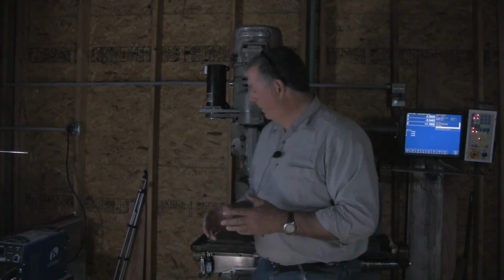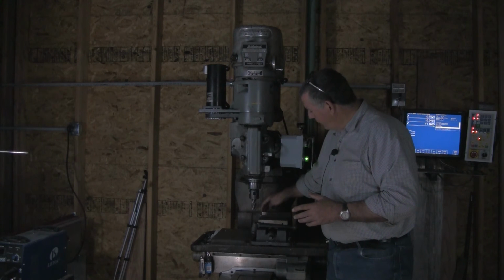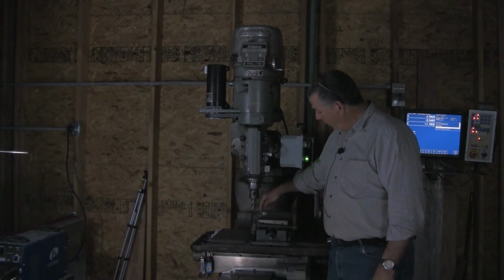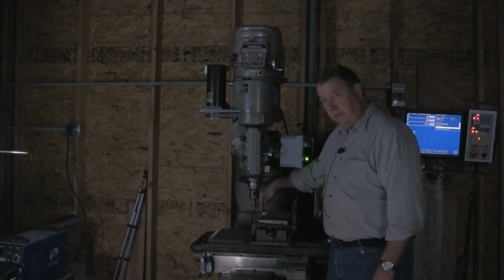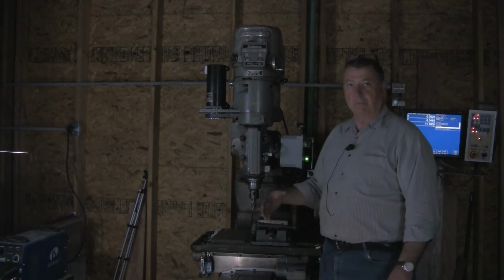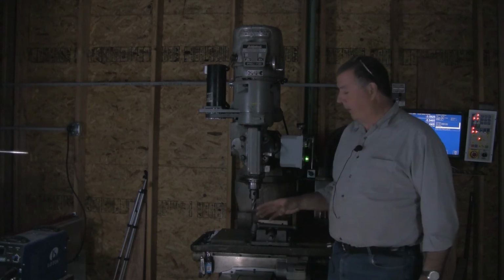Also, if you do set up other work offsets, let's say, as you can see here, I have a vise mounted to my machine. If I set up an offset for G55 that goes from this back side of the vise and this corner of the vise, and I tell it that this is 0, I can now set a part in there. If I'm going to cut multiples of that same part, I don't have to re-zero every time I go to cut that part.